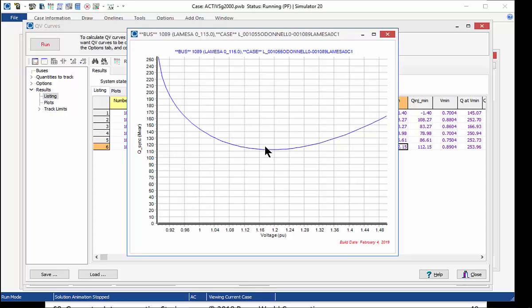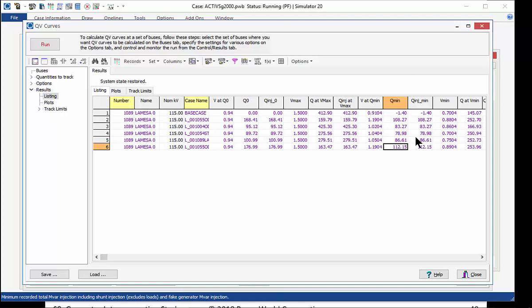So if we just wanted to dive into this issue a little bit deeper, we might say, well, what if we put some reactive power support of at least another, say, 120 to 200 megavars at that point of interconnection? Would that allow us to be stable at higher transfer levels? But you also might conclude that the thermal issues are much more limiting. So resolving those might beef up the system enough that the voltages look better.